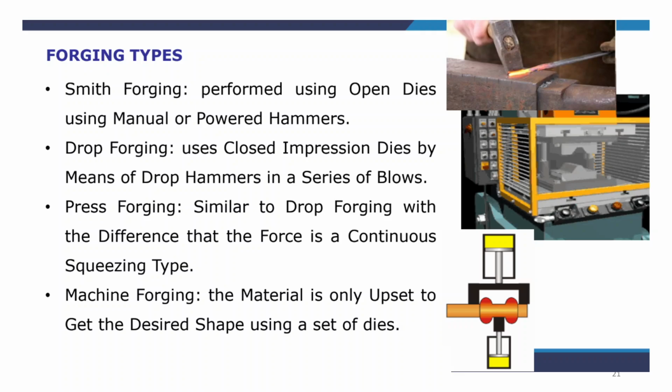Will the recrystallization temperature be greater than the melting point temperature or lower? It will be lower than the melting temperature. All these processes that we are reading are being done below melting temperature, of course. The recrystallization temperature is 0.3 times the melting temperature. You multiply your melting temperature in Kelvin by 0.3, then you will get the recrystallization temperature.